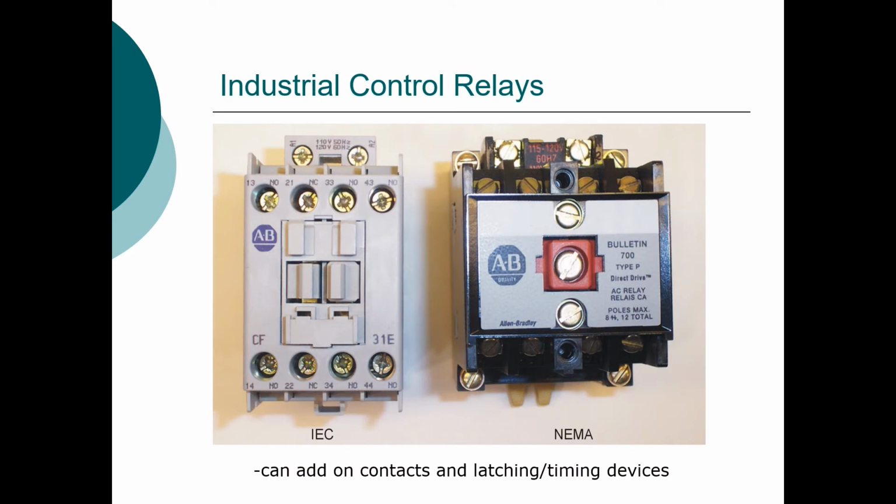For heavier duty applications, we would use an industrial control relay, and these are commonly used for switching circuits with lighting and motor controls. An advantage that we have with the industrial control relays is that we can put additional contacts on by putting on what are called add-in decks.